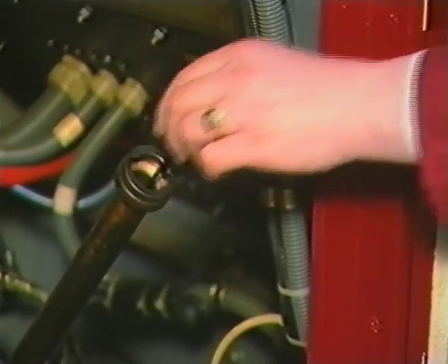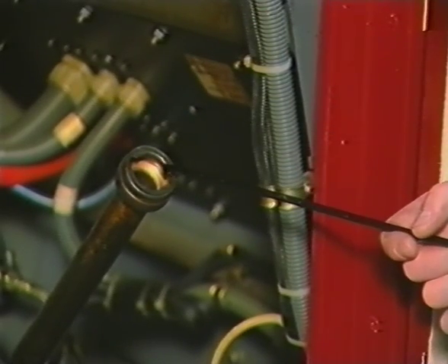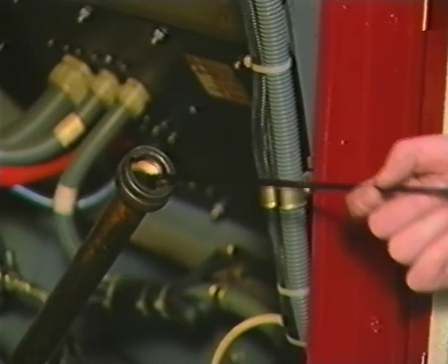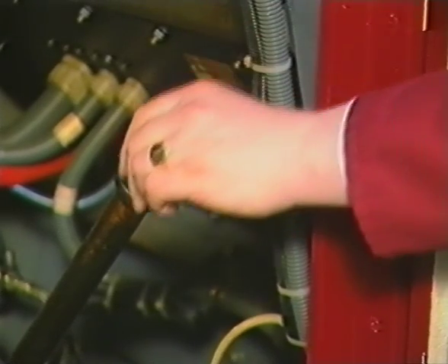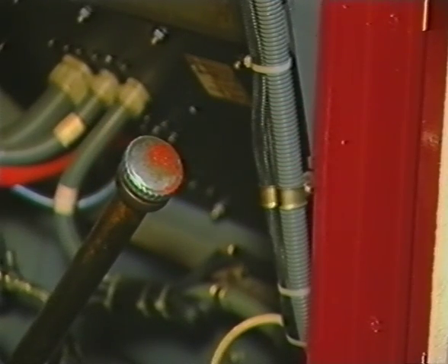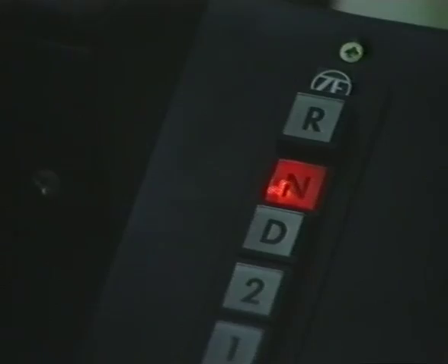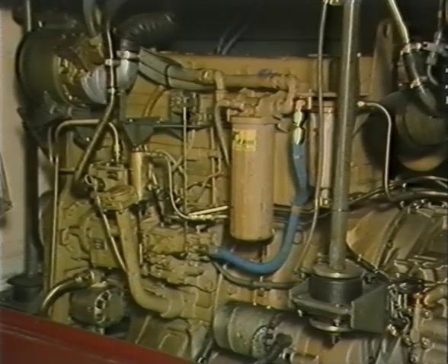Before proceeding in this fault category, it is important to ensure that the gearbox oil specification is correct. Use of the incorrect oil can cause the frictional characteristics of the gear clutches to alter, causing harsh engagement. It should also be noted that if the engine power is down substantially, this can again cause harsh engagement. Therefore, start the engine, engage D, and accelerate the engine to full throttle.